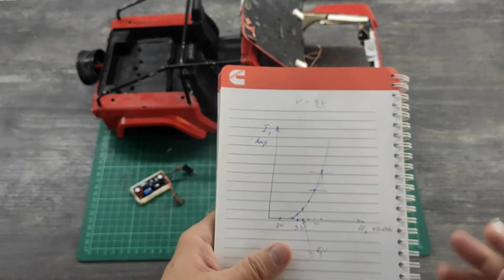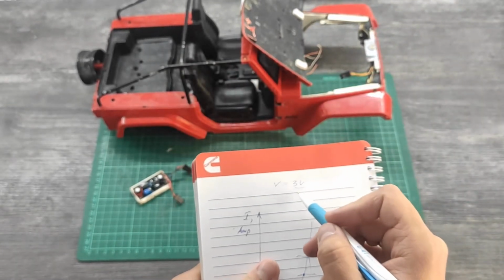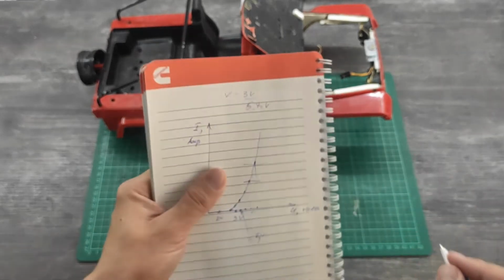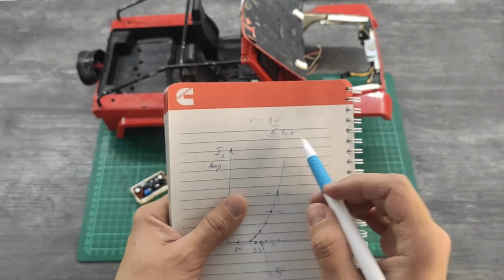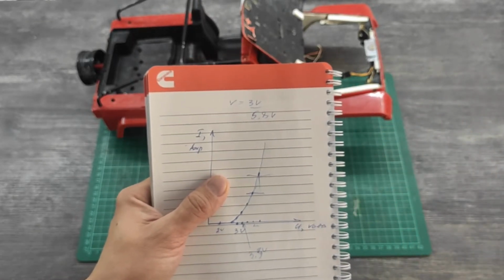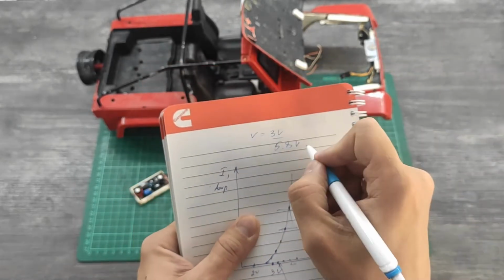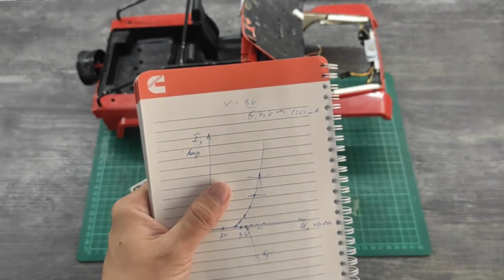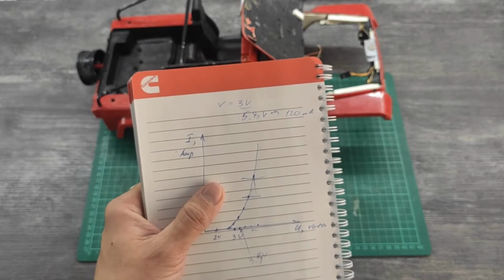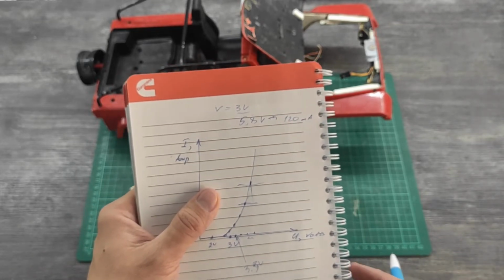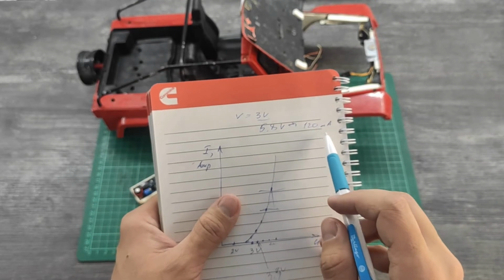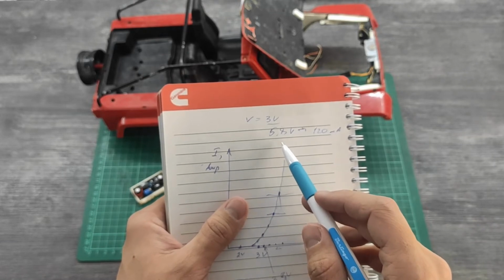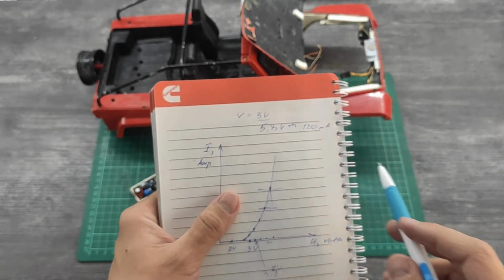As I have 3 volt LEDs, I applied initially 5.8 volts and measured the current in the circuit. It was like 120 milliamps, I believe. I left the diodes emitting light for a couple of minutes and checked that the current doesn't change, so it doesn't increase. Further on I used 6 volts, 6.1 volts, etc., just to check.